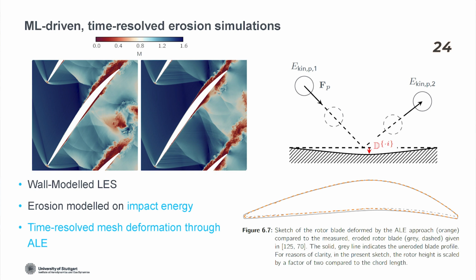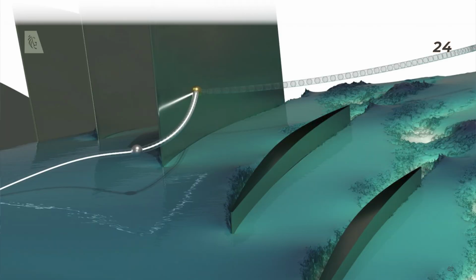And to me, this is really amazing, right? Because we have a complex flow. It's compressible flow. There are shocks in there. There's turbulence. You can see a snapshot of the flow here. Things are moving around, and we're using machine learning just as a helper to bridge this scale and improve the model that gives us this particle wall interaction. So this is one example of where you can use machine learning in such a modern CFD solver.